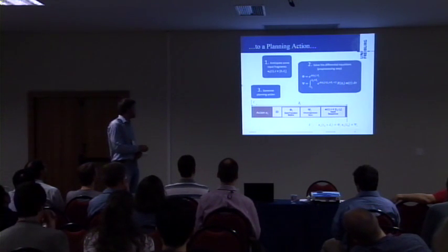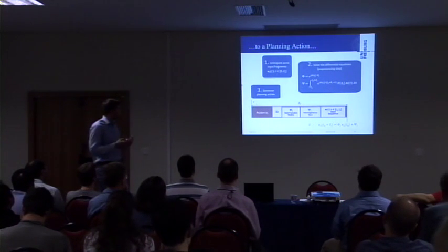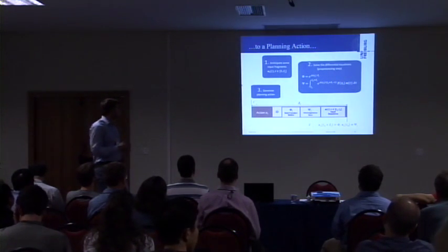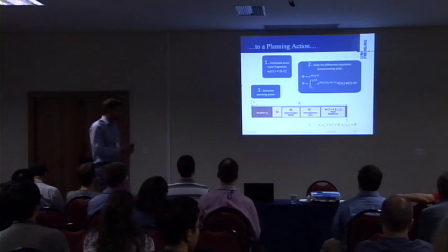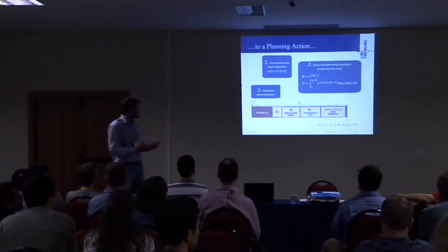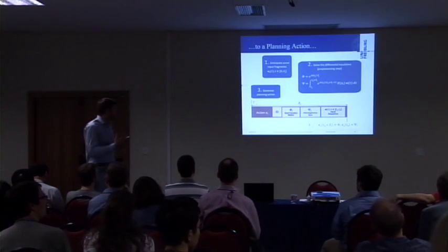We store the information about the homogeneous solution here, the state transition matrix, defined by this matrix exponential function, and the inhomogeneous term, which is basically the impact of the anticipated input fragment, obtained by the convolution of the dynamics with this anticipated input fragment, and finally the input fragment itself.